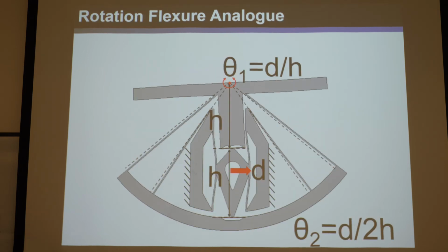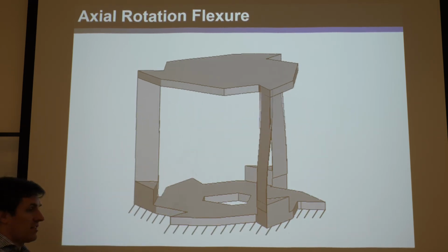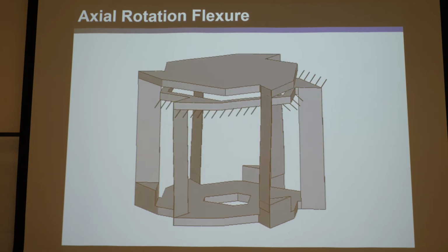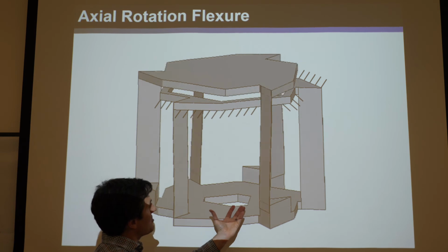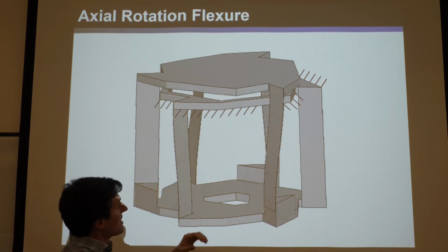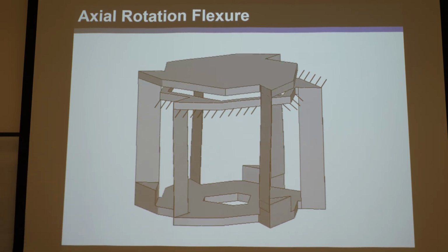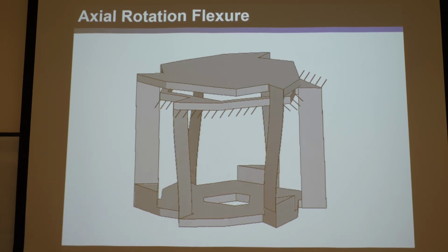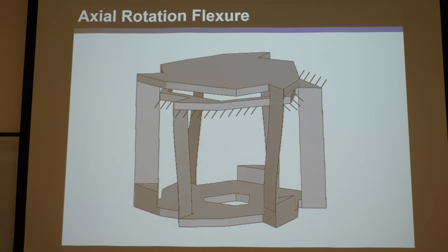and help get rid of some of the parasitic error. You know, in this case, as it rotates, it actually pulls down a little bit. It actually screws down. You don't want that, right? And so with this, as this guy rotates, it actually screws up a little bit, and this rotates, it screws down to the point where this doesn't move. But that's only if it's the 2-to-1 ratio, which this does not enforce. So still, same footprint size, twice the range capabilities, it fixes parasitic error a little bit, but still slight parasitic error.